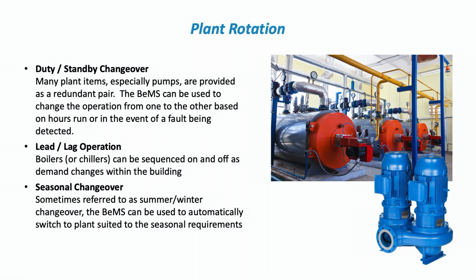We can also use our BeMS for plant rotation. Duty standby changeover means that if we have redundant plant, i.e. a twin-headed pump, as is shown in this drawing here, we can rotate that plant so that we can give it even wear, or we can have one designated as the duty pump, and we can run that, and then if it fails, we can switch over to the standby pump.